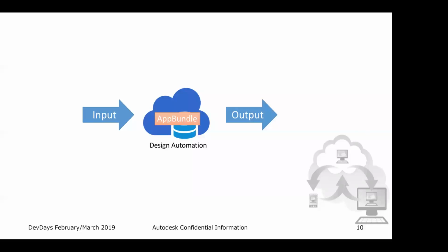The bundle is telling what will be done inside your Design Automation processing. So on the sample we showed before, the app bundle defines for that specific engine and version, and the bundle contains the DLL and all the supporting files for that plugin to run. So the plugin is very much similar to plugins we post to the App Store, and usually contains a package contents.xml inside a bundle folder, also contains the DLL, and in some cases the add-in file.